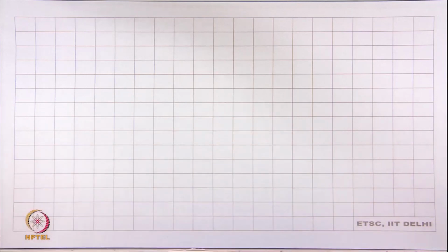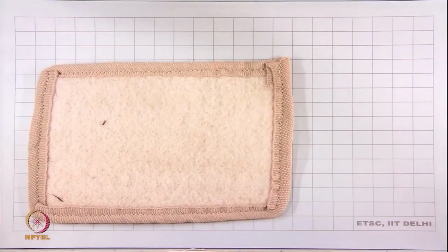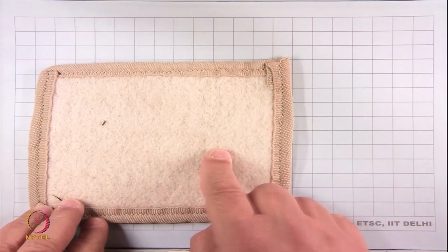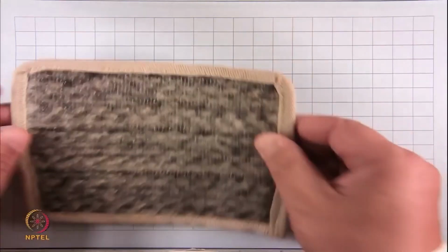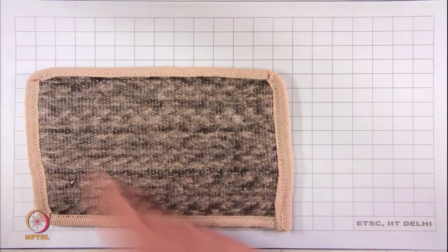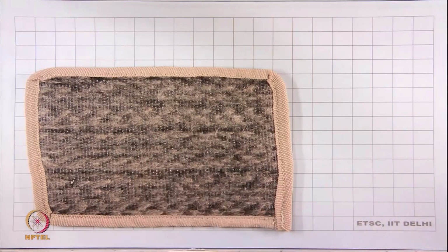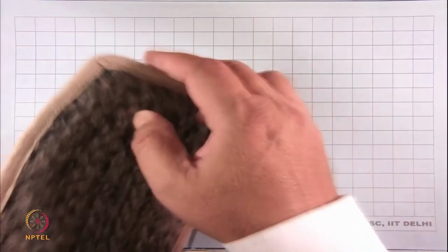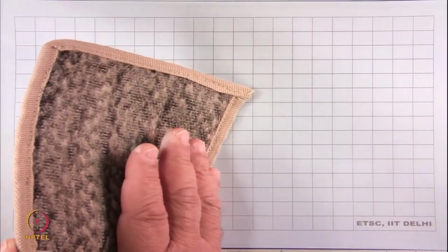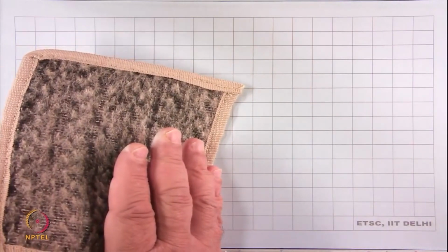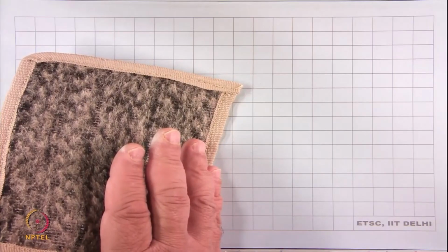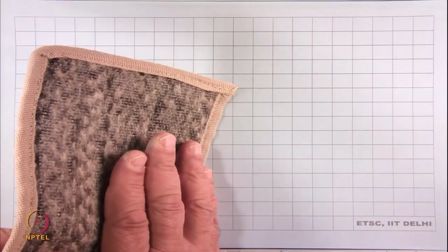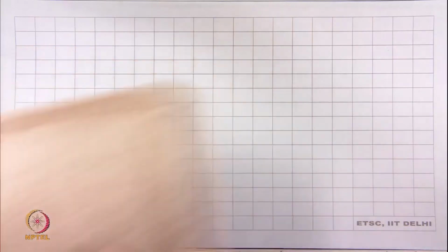And now I'd like to show you a GCL. This looks like the non-woven geotextile on the top. I flip it around. This is a non-woven or a woven geotextile at the bottom, or a hybrid. Between the two, if I look at this, this is stitched together, but between the two is bentonite powder, right? And it's about 5 millimeters thick. This is one type of material.